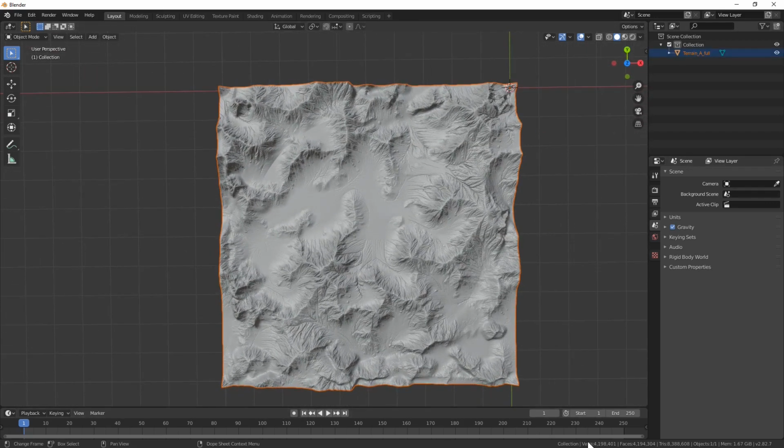This mesh has over 4 million faces. Far too large for many tools to handle. Converting it directly to Collada and loading that into SketchUp version 8 takes, well, I gave up waiting after 8 hours. We need to do something to reduce the complexity of this mesh.